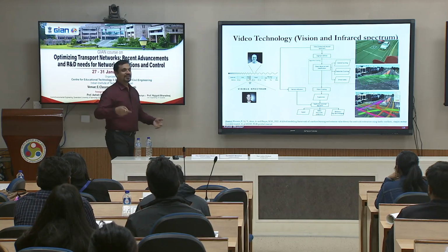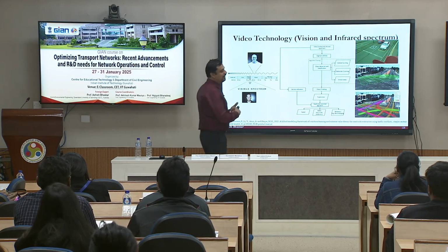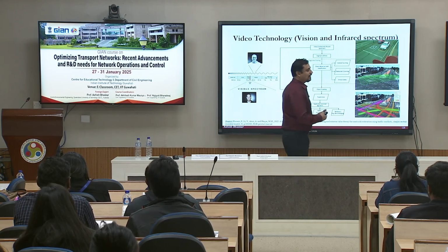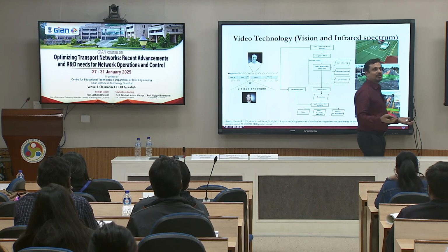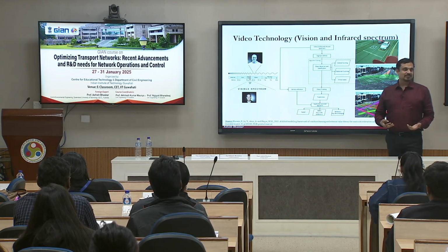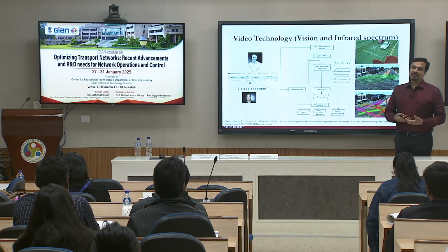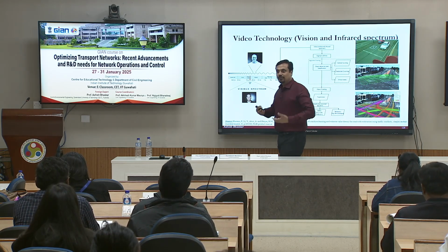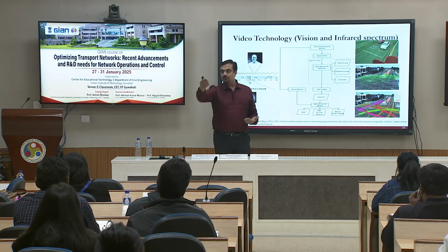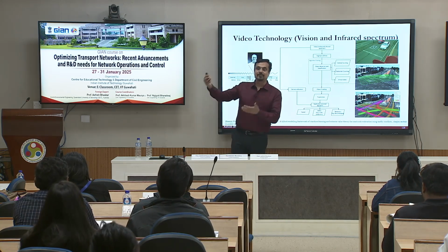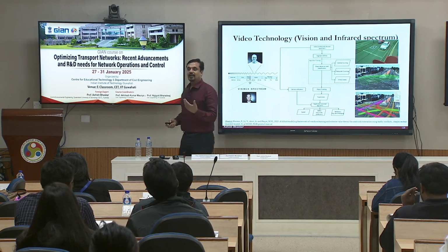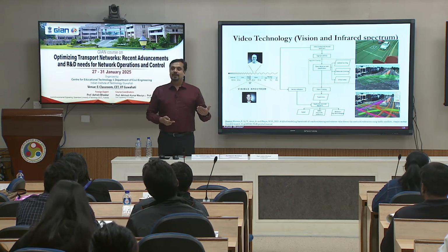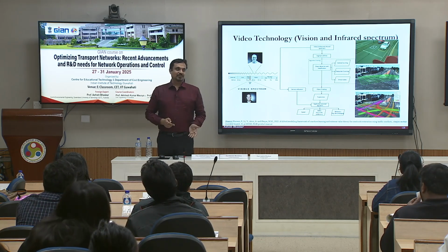That's good. So at least the other thing which we have not even explored here is a lot of information you can get from, let's say, Google-based travel time or some other travel time sources, which are expensive to buy, but available. Perhaps you can get it from other sources also. If you get the crowdsourced travel time information from some third party, that can help you think of how you can bring that knowledge into your signal optimization.